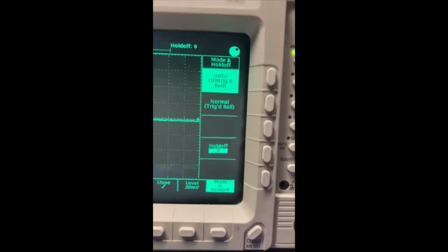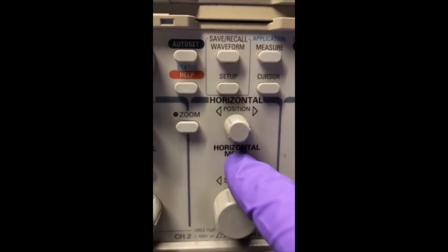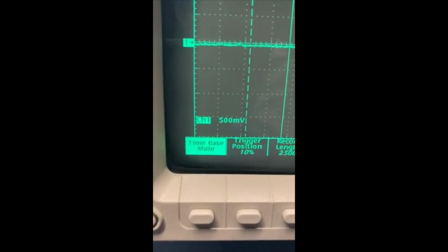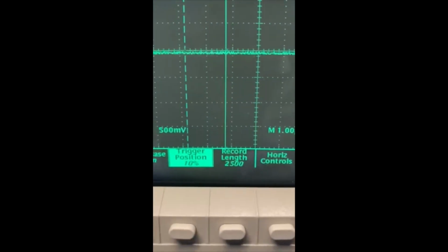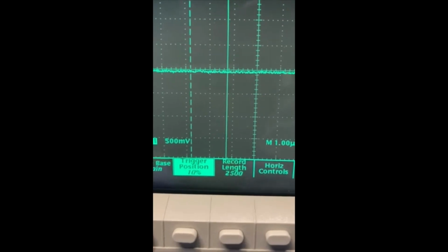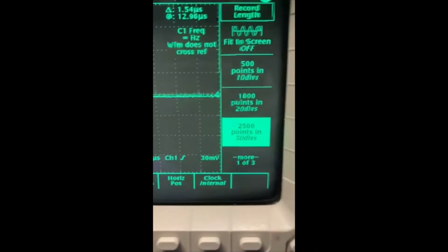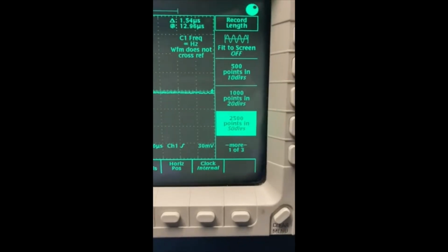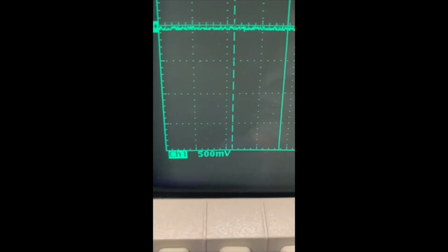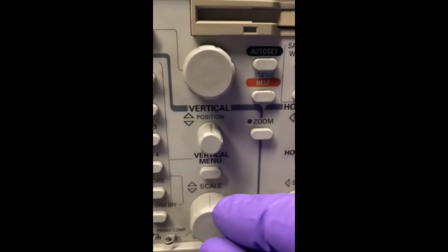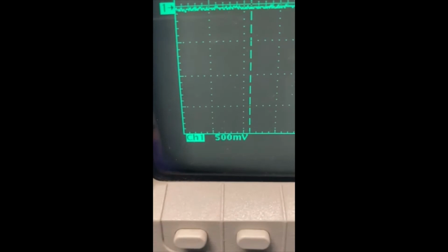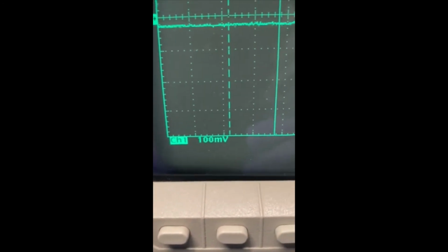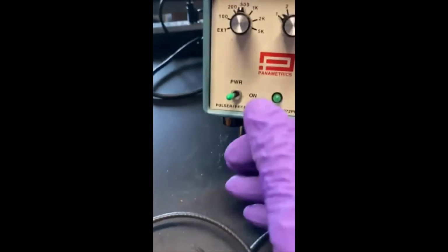We have control over the scaling of the horizontal axis so that we can separate out the pulses in time with sufficient resolution to be able to accurately determine the time delay between the pulses in this video. We'll be able to see all of the different controls that we have for positioning the signal, scaling the signal in both X and Y, capturing the signal, and then being able to make measurements between the pulse that is transmitted and later received from this data.